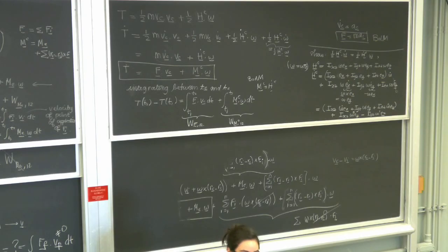Now problem 5 is a little bit more complicated because it consists of two rigid bodies. To write the work energy theorem of a system of rigid bodies, we have to write the work energy theorem of each rigid body and add them. Be careful. So draw the free body diagram of each bar, write the work energy theorem for each bar on its own, and then the work energy theorem for the system.